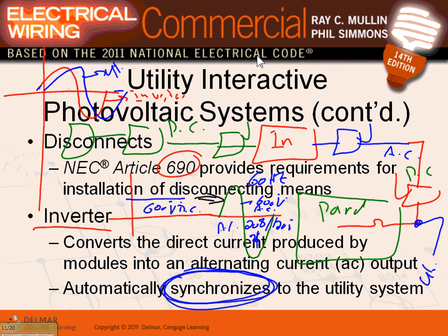Like for generators, it's like driving your car at 80 miles an hour and putting your gear in reverse, if you can, or putting it in a lower gear if you have a manual car. What happens to your gear? It's going to bust. So that's equivalent to connecting two systems together when they're not in sync. Okay, so I can't emphasize the word synchronization enough.